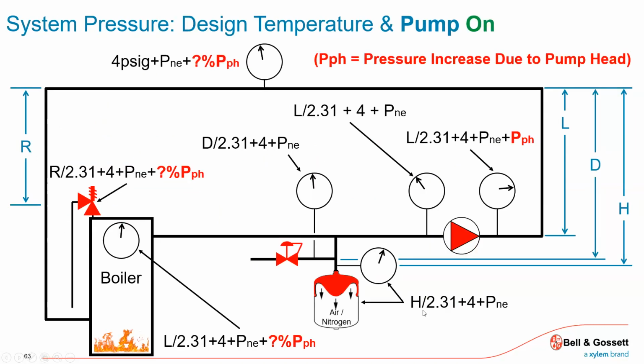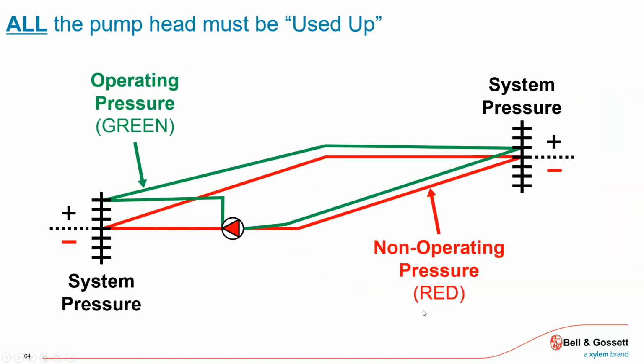right at that discharge, and you put gauges across the system, you're going to see it slowly drop. Why is it dropping? It has to. Yeah, friction. I'm eating up the energy of the pump head that I had calculated that I needed to move that flow to overcome the frictional resistance of my heat exchangers, my fan coils, my piping, all the above. So what that's trying to reflect here is, it's not that maybe the pump went to 0. He just went back to non-operating system fill pressure, that red. But everything that he can develop gets eaten up.